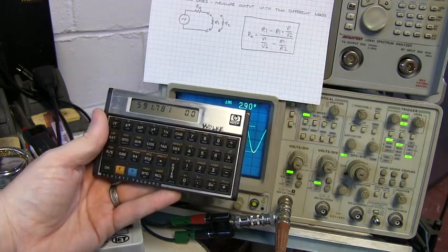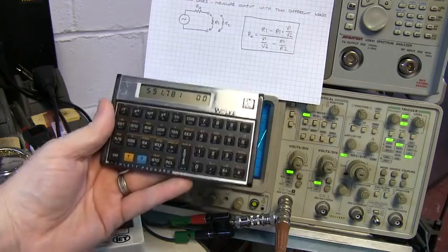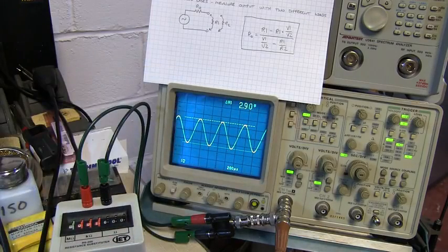So I'm only about 8 ohms off out of the 600, but you can see that that method works as well. And again, this will work for situations where you want to put the amplifier or the circuit in a mode where it's operating close to its normal operating quiescent point, so that the output impedance of the transistors and things like that are all what you expect them to be under normal operating conditions. So this is a little bit more of a general case, being able to just measure the output amplitude with two different load impedances, and then calculating the output impedance from that.